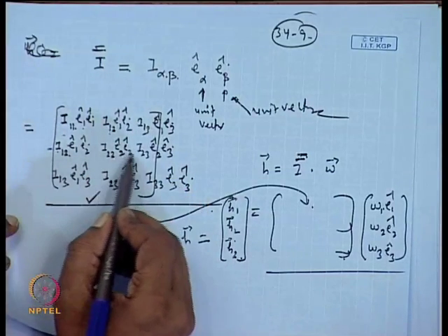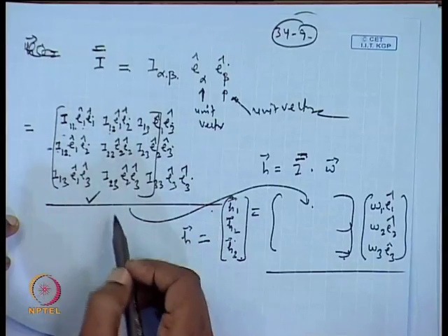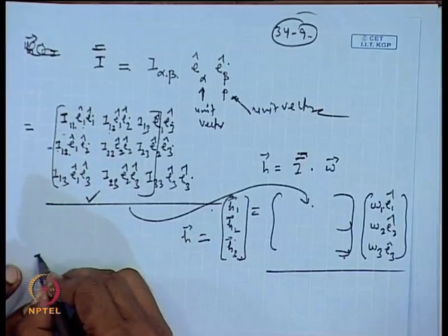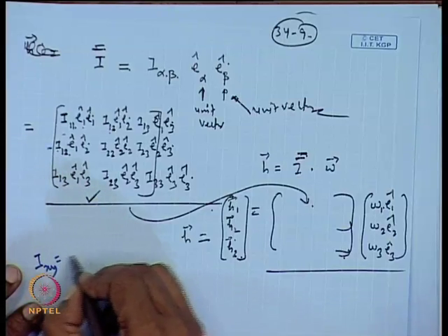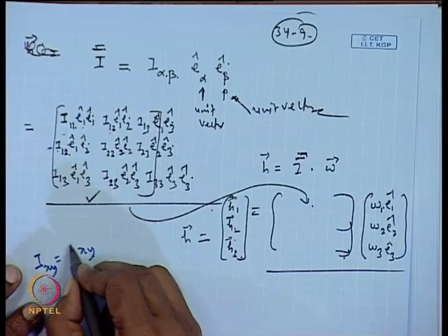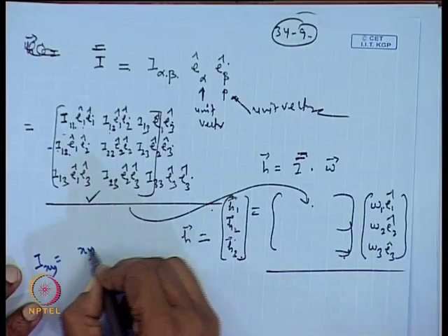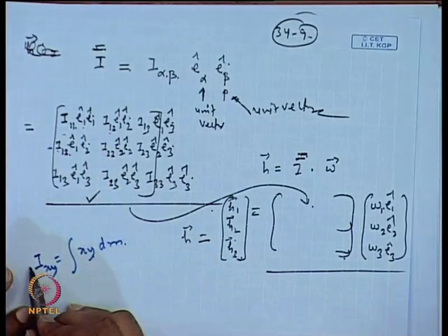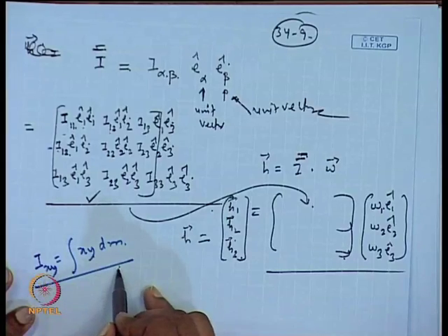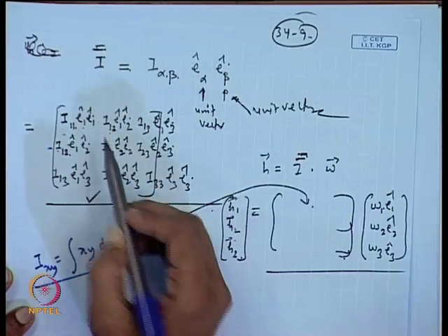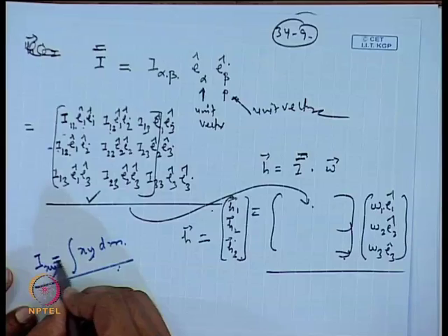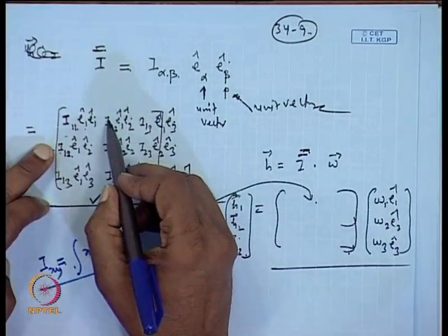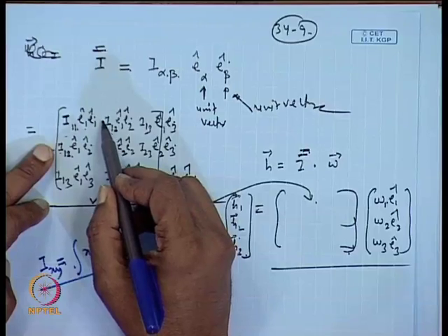and similarly the negative sign before these off diagonal terms. So, why am I suggesting that? Because once you write the cross product of inertia, say you write Ixy, this is x y times the mass. So, if you write it in this way, then you need to put a negative sign before this, but if you absorb the sign in this place, then you can keep the positive sign here.